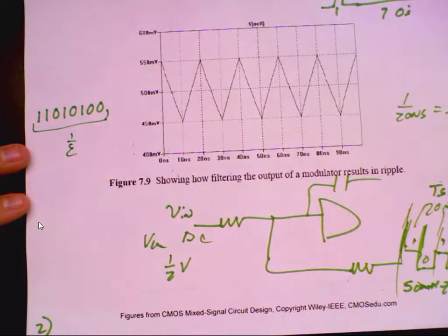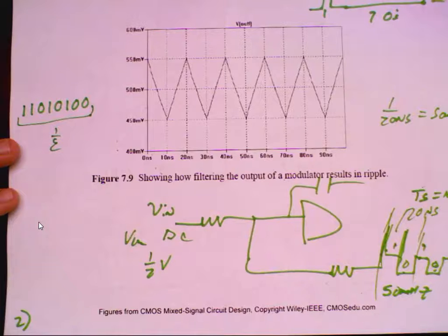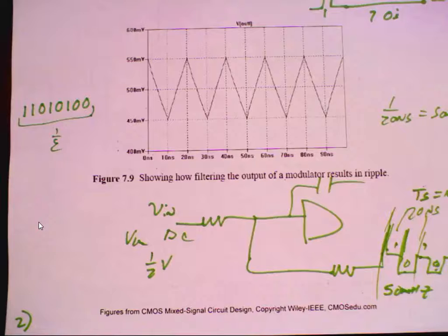Now I just showed you a dither source. What was the more common way that we could do that by changing the topology? Yeah, use a second order modulator. With a second order modulator, the tones in the output are much less of a problem because it randomizes things. So you get things not repeating in sequences, but it averages out to the same value. Is everybody clear on that?